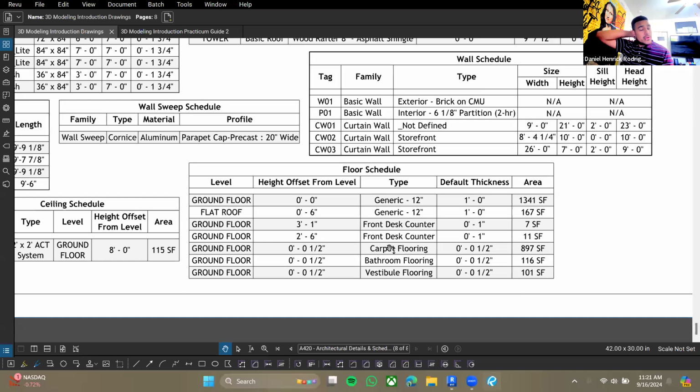So whenever you create, let's say, a kitchen, it is often that the kitchen will be planned and it won't just be a standard shape. So how does making a kitchen in Revit work? For example, you're gonna have all the casework, and that's the name of the folder. If you're ever making a kitchen, that's the name of the folder. You're gonna have casework where you're gonna have different cabinets, and you can put these cabinets down whatever shape you want, and then to make a countertop very easily, what you can do is you can make a floor, because guess what? Floor is just the name of the tool.